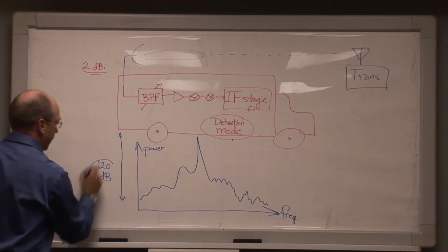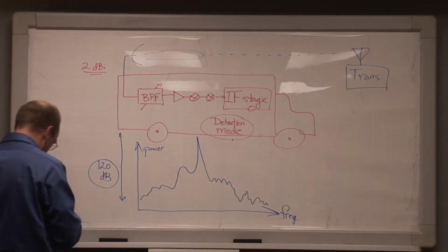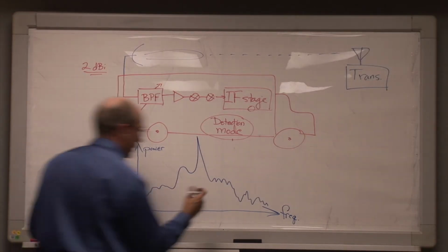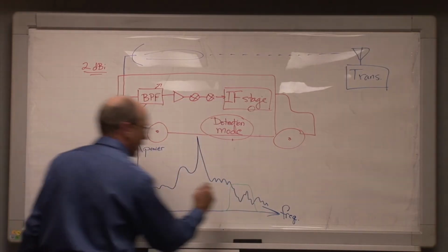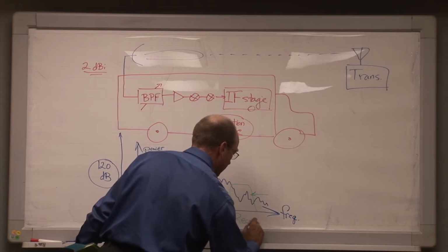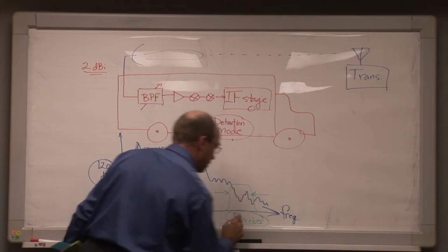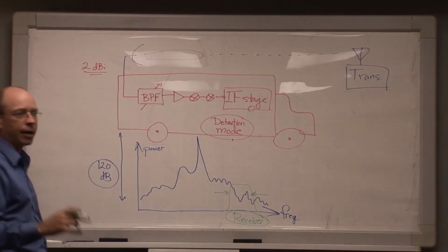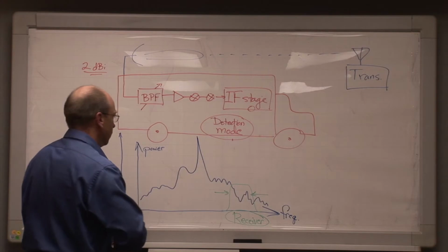But in any event, we're going to try to get a wide dynamic range measurement, which also presumably will cover a lot of spectrum. And in particular, what we've just got to get is the spectrum across whatever the band or the operating frequency range is of the receiver system that has had or has reported the problem. So if this is the band or the frequency range across which the receiver works, we've got to get the spectrum across that range.